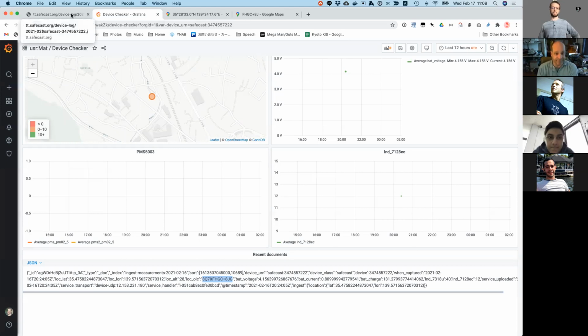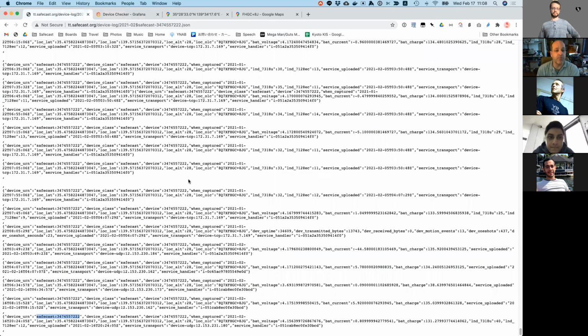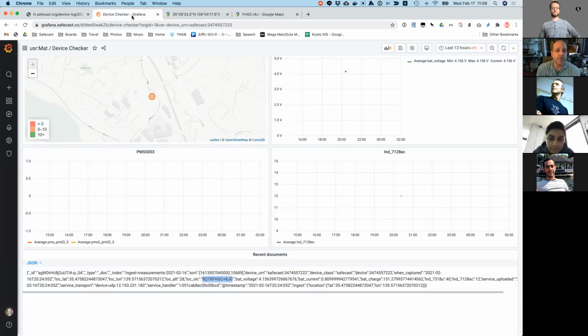Great, awesome. I will modify the hardware inside the box to put power on the low power memory for the GPS, so that it remembers its location after it gets a fix. I think the firmware lights up the GPS, and if it doesn't get a location within 90 seconds, it uses something it has stored.